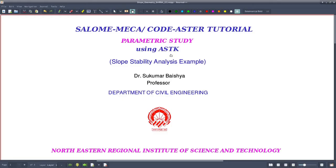And there is an interface called astk, which you can invoke either from Code-Aster or from the Salome-Meca interface. In astk, it becomes pretty easy to conduct parametric studies, and our basic objective is to show how we can use astk for doing the parametric study. To illustrate this, we are taking a slope stability analysis example. We'll try to find out the factor of safety of a particular slope. Okay.